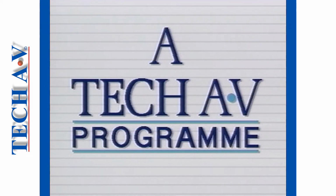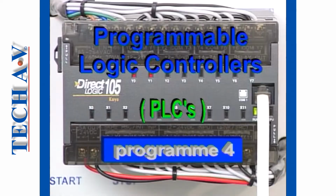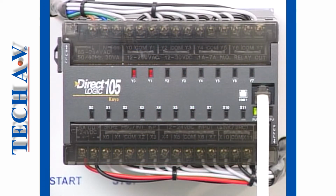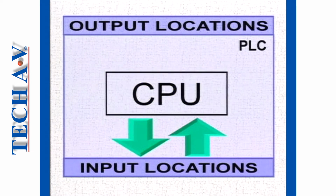The producers and distributors of Tech AV training material welcome you to the fourth module in a series entitled Programmable Logic Controllers. In this module, we shall be discussing the PLC as an information processor, and you will learn how it handles information by checking and recording the state of each input location, deciding the state of each output, and then activating the outputs.